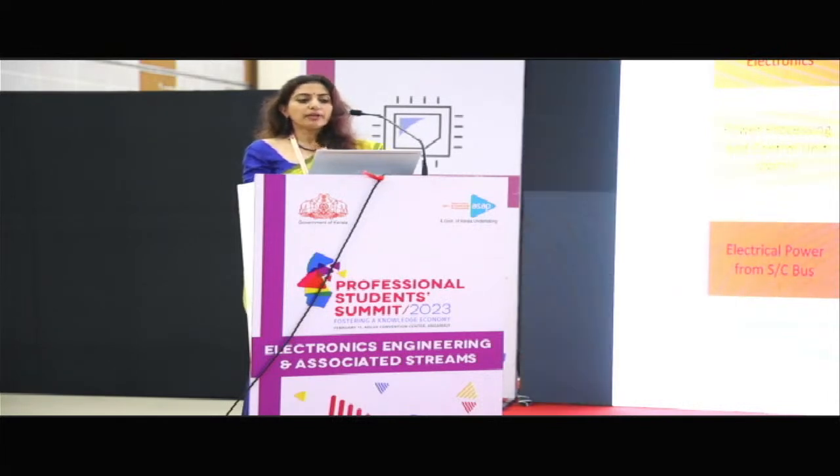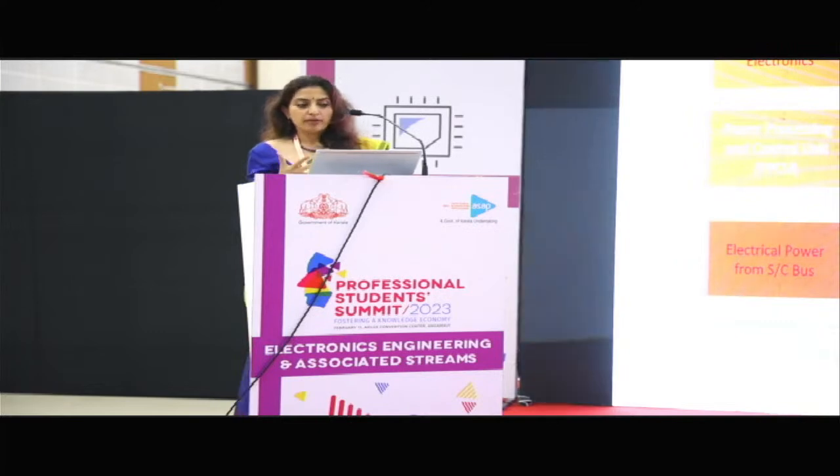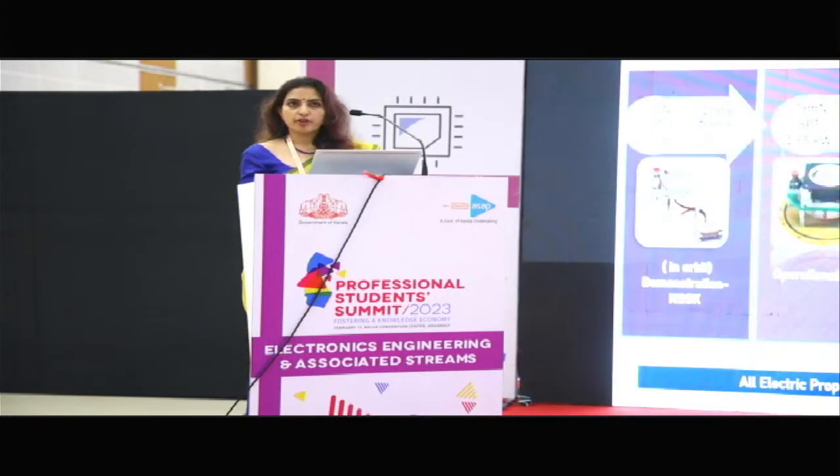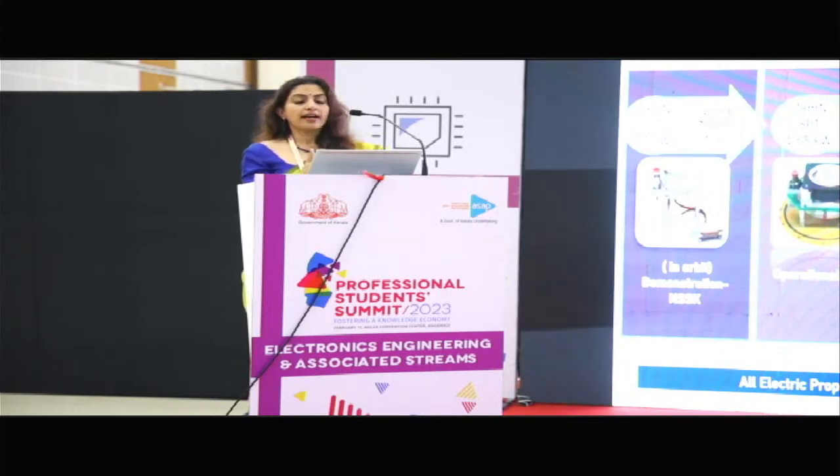Okay, now coming to the development of electric propulsion, as I told, we are working on all these elements to make them indigenous. We have the 18 millinewton SPT, and we have done up to 121 hours of cumulative duration, and we also have the 75 millinewton SPT, which worked up to this much duration. Now we are working on the 300 millinewton SPT, and it has exceeded 310, it's around 400-500 hours cumulative now. All the development is completed, and the qualification is at an advanced stage.